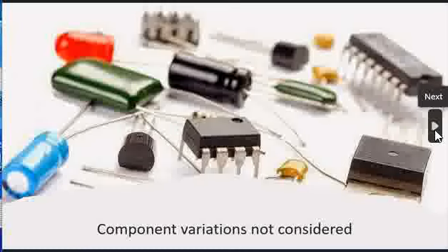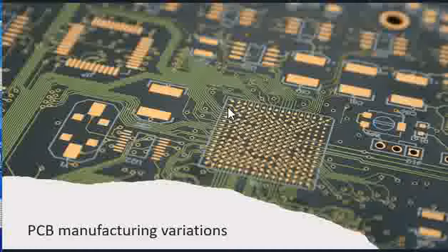as an end product. And then PCB manufacturing variations. This is similar to what we have discussed. Achieving the exact trace impedance is not at all possible. That's an ideal scenario. That's a dream, basically. We have to live with those variations, and the PCB manufacturer quotes that and gives those in their specifications. So that definitely is not considered as a part of the simulation,